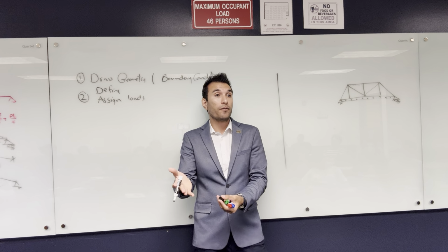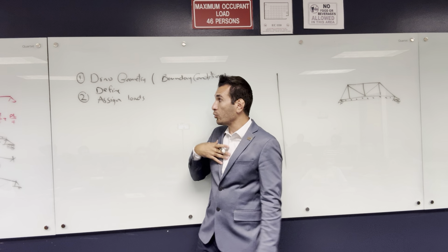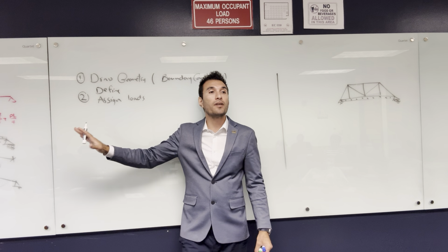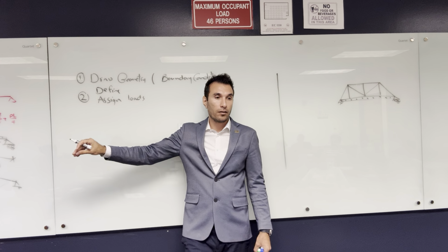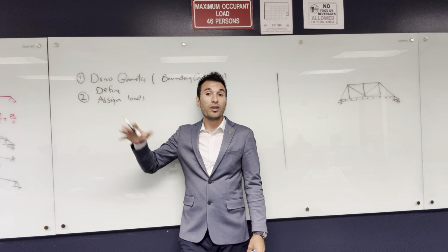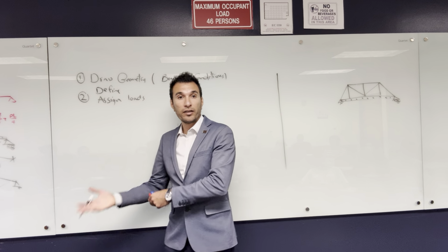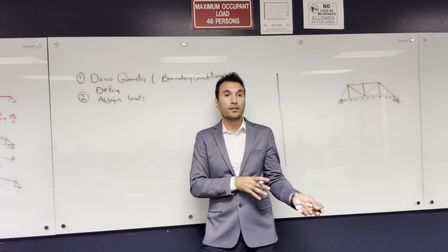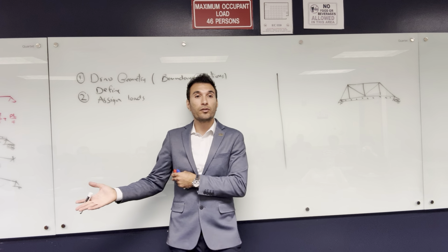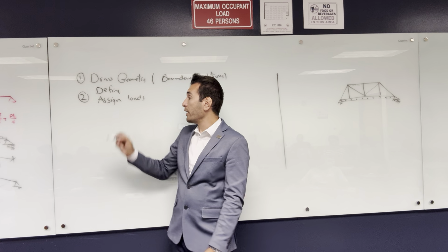If you want to let the software do the own weight part, yeah. Usually, when I define dead load, I leave the own weight inside the dead load. So it's up to you. You want to calculate the dead load by yourself, the own weight, and then assign it on the structure, or you want the software to do it for you.